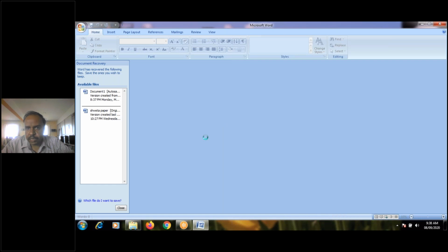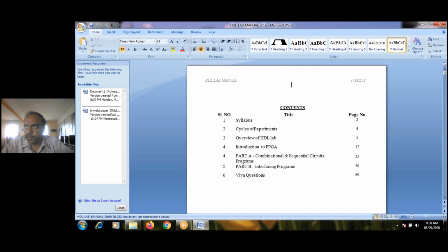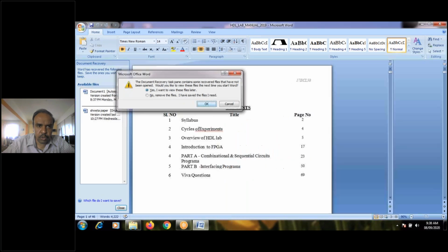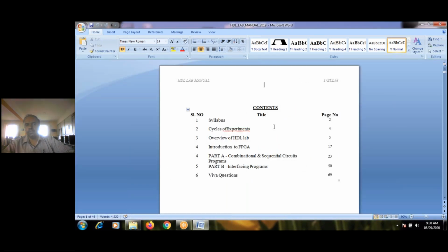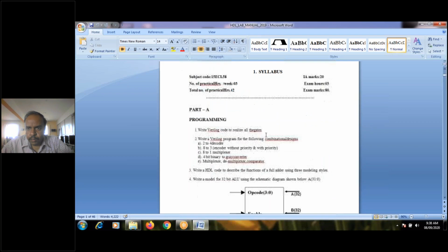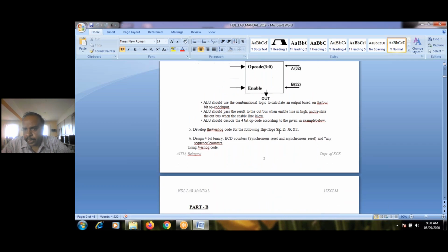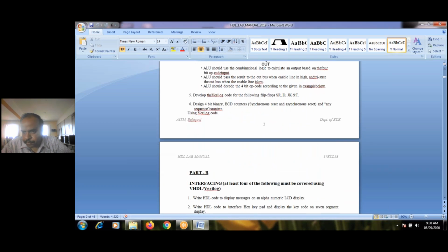So what happens is, in case of 3 to 8 decoder, how many inputs you may require? 3 inputs, say A, B and C. Correct. And what do you require along with these 3 inputs? What else you require apart from these 3 inputs? You require one more input. That is called as what? Any answers? Enable. Yeah, fine. Enable is one more input, right?